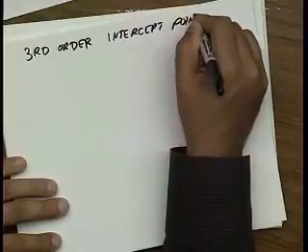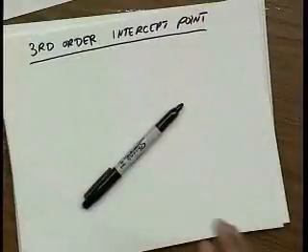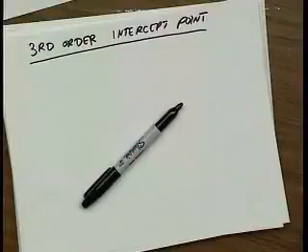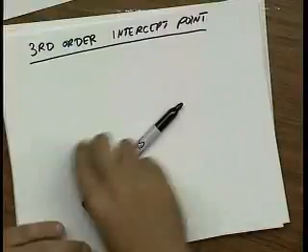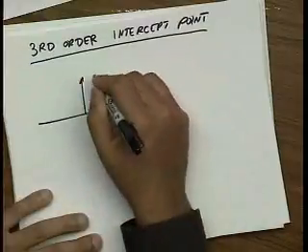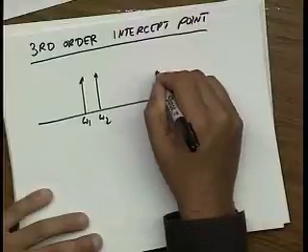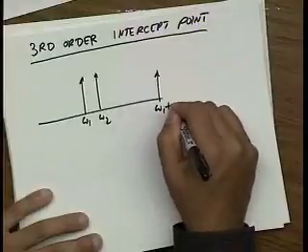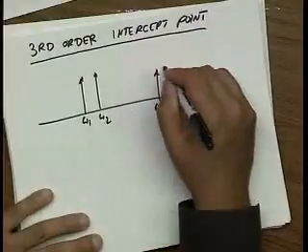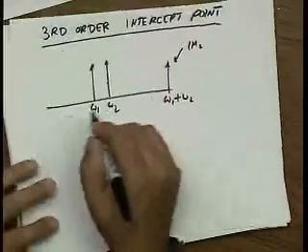Remember last lecture we talked about second order intermodulation falls at low frequency and at roughly twice the frequency if you have two tones, right? So if you have tone omega 1 and omega 2, then we had an omega 1 plus omega 2. That was an IM2 product.